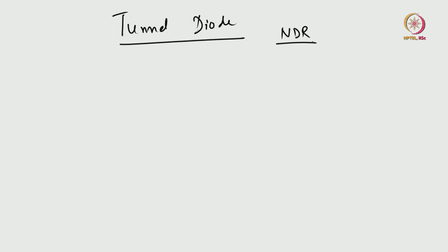So over to the whiteboard. First we will talk about the tunnel diode, and after that the Gunn diode. As the name suggests, the tunnel diode uses the quantum mechanical process of tunneling to get a negative differential resistance, NDR. If you recall, in our impact diode we talked about a negative differential resistance in the AC signal, where the current and the voltage are out of phase, with a phase difference of around 180 degrees. Because they are out of phase, we call that an AC negative resistance, and we use that to generate oscillation.